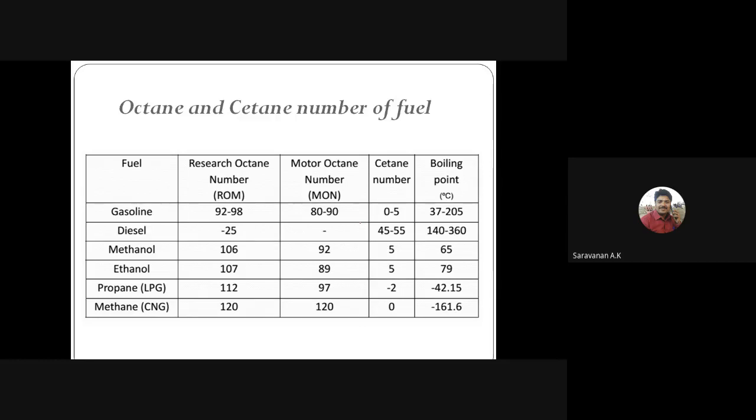So the compression ratio of the engine also strongly affects knock, right? A higher compression ratio gives better thermal efficiency, which will be discussed in the next class, right?